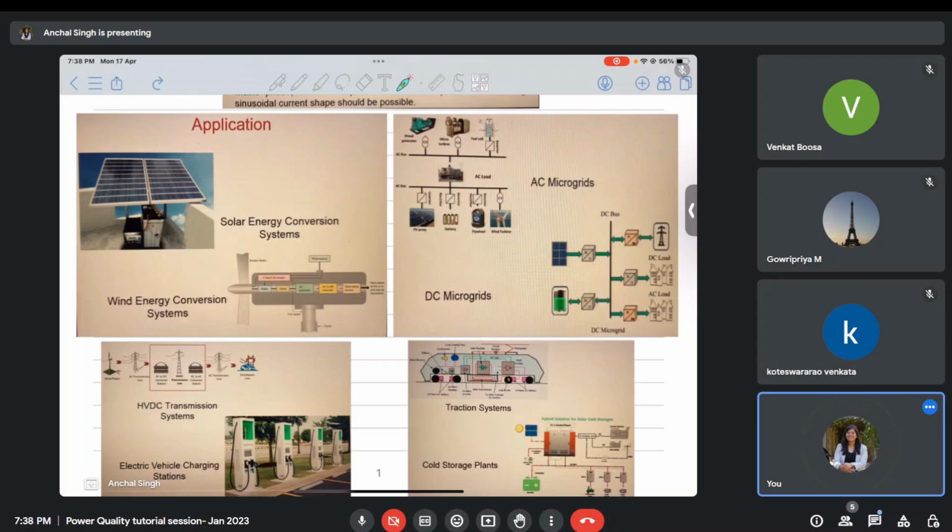In our houses we have a single phase solar energy conversion system, but in solar fields we need to increase the number of phases because high power has to be transmitted to the grid, and the grid in all these areas is mostly available in three phase form only. We could connect the single phase to that three phase also, but the more efficient way will be connecting directly to the three phase AC supply, because we have a very high amount of power to transmit, right? Therefore we increase the number of phases, and therefore these large solar fields and wind energy farms all have three phase converters.